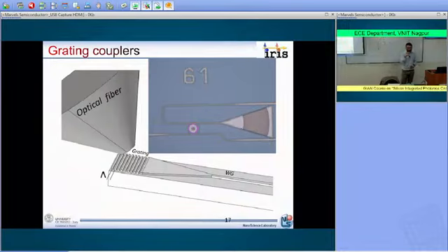And so during the optimization, during the design, I know that you are doing some design in your courses. Those are aspects that you need to take care of. You want to optimize the quantity of light that is reaching the waveguide here. And therefore, you have to optimize the shaping, the curvature here, in order to focus the light there, as well as you want to avoid any loss in this part of the grating. And therefore, you have to carefully design the tapering.